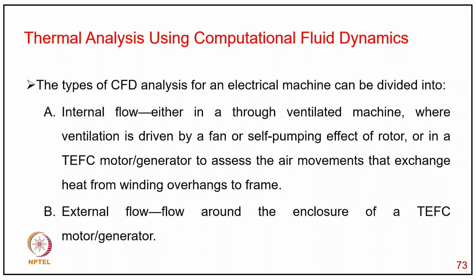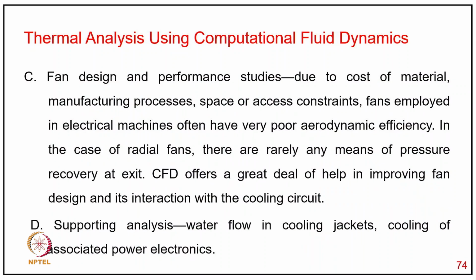Then the types of CFD analysis for electrical machines can be divided into parts. A, internal flow, either in a through-ventilated machine where the ventilation is driven by a fan or the self-pumping effect of the rotor, or in a totally enclosed fan-cooled motor generator, to assess the air movement that exchanges heat with the winding overhangs and frame. And B, the external flow around the enclosure of a TEFC motor generator. The C is fan design and performance study.